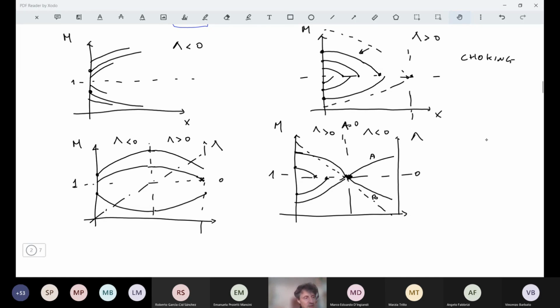Well, this is known for converging-diverging nozzles, if the driving potential is the area change, and we have to consider here the throat, where dA is equal to 0. So it's lambda equal to 0 too, but in general this is true in different positions and also due to other phenomena like friction and heat exchange, so increase or decrease of the total temperature. So in principle we have different conditions that lead to this choking.